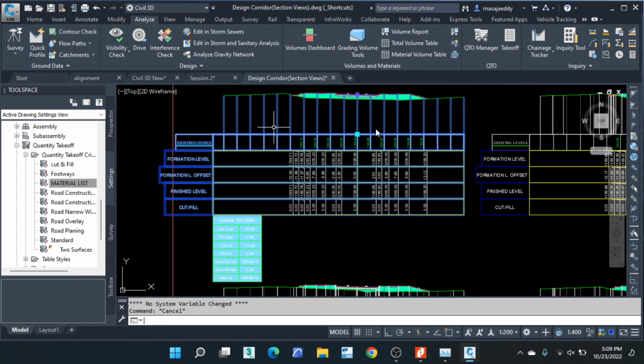Let me use the detailed design profile labels coordinates. Okay, I select OK. Then the chainage edges. I'm going to have sheets with chainages of 0 to 500 each sheet, so I'll press OK.